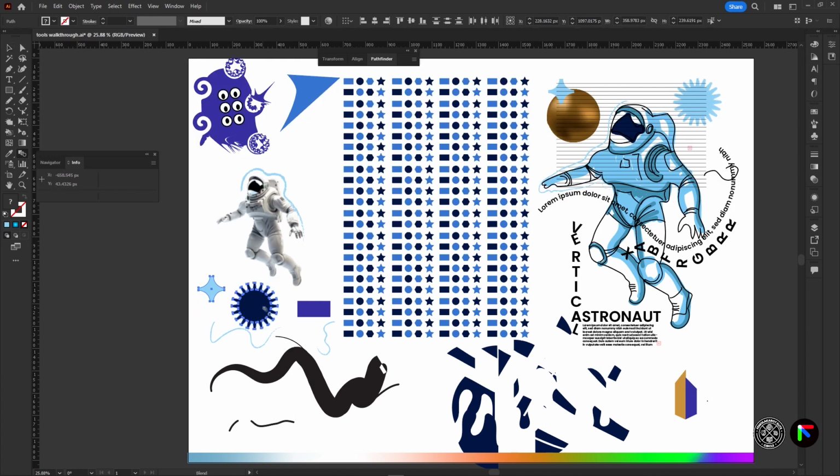So all you need to do is just click once, right? But let's double click to check our settings. So you see, we have different settings. It can be smooth color, specify steps, or specify distance. I can decide to choose any one, but most times I choose either specify steps or specify distance. So let's do specify steps. I want about 50 steps, and I want it to be like so, and then click OK. So once I click in between, I have that.